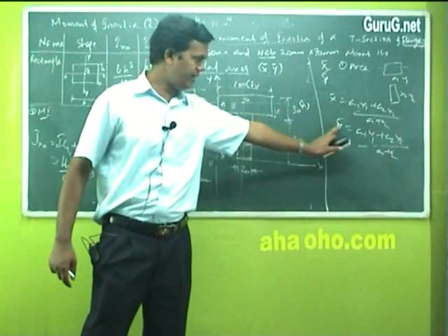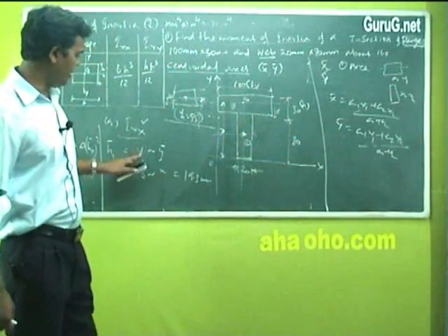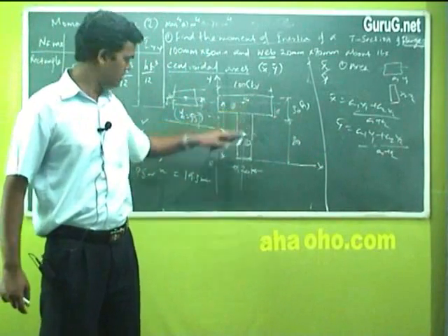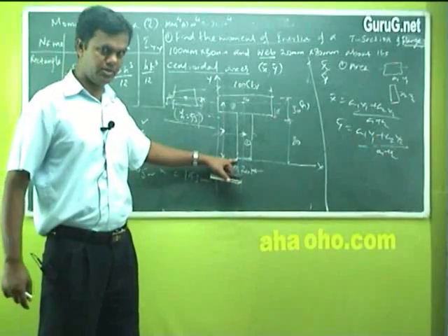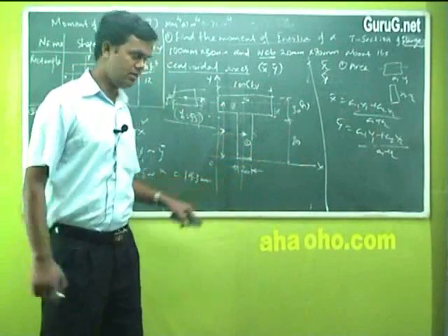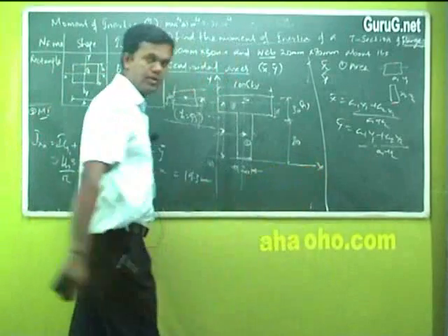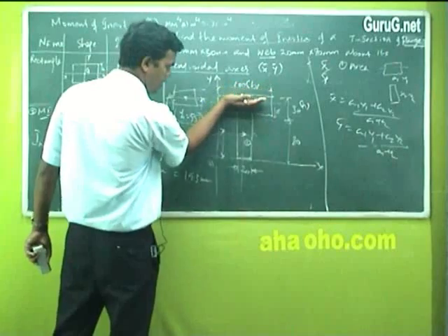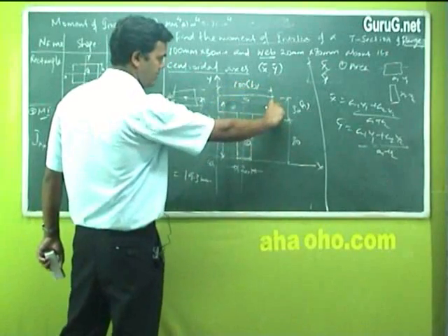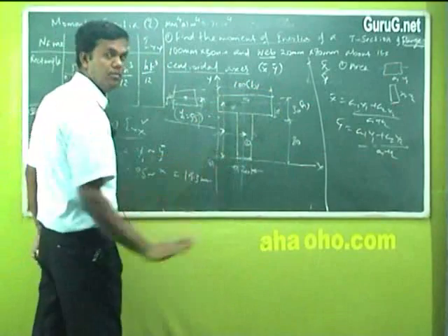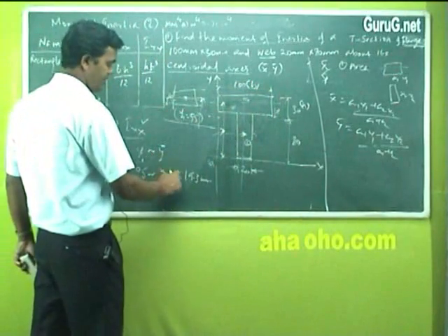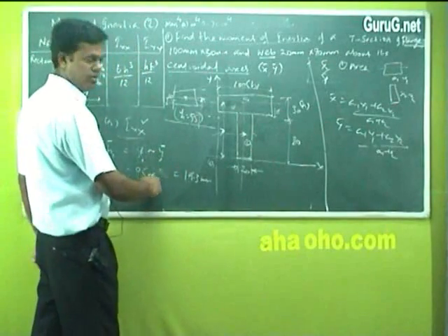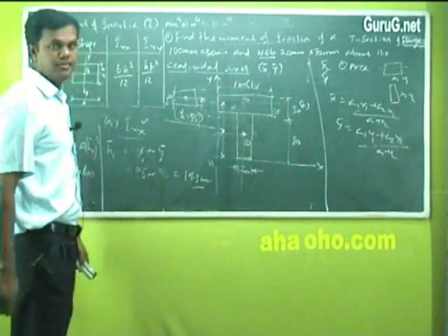After finding Y bar, Y1 is the center point of portion 1, 95 from the base, from the OX reference axis. That is, the centroid CG of sketch 1 is at a distance of 80 plus 15, 95 millimeter from the bottom. The difference of that 95 and your Y bar value gives 19.3 millimeter.